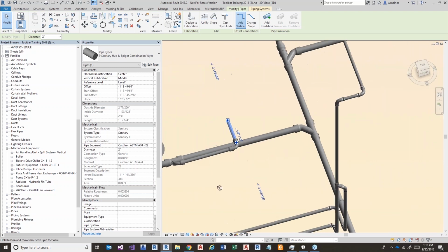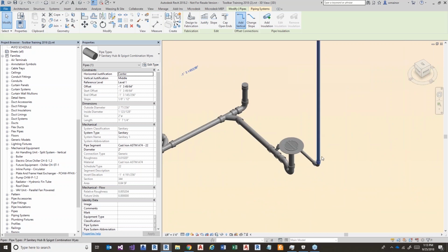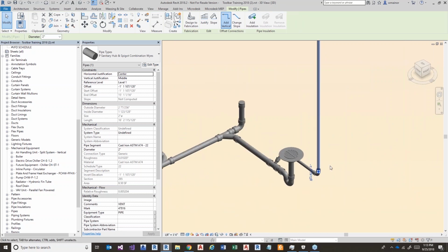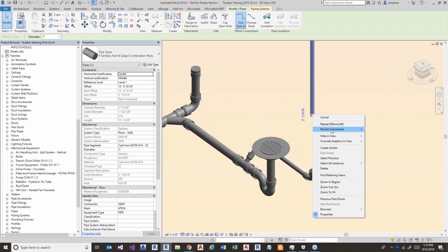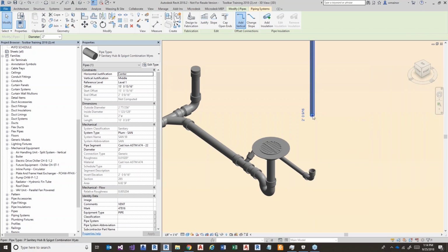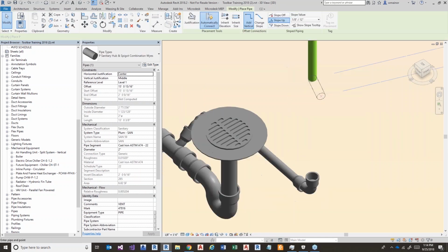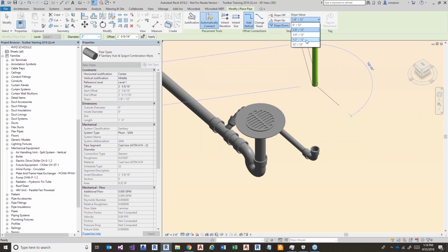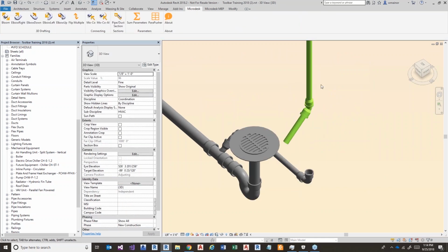So eventually what I'm thinking is I probably have another vent line which I need to come off at a 45-degree angle. So let me just come up here. I'm going to pull this guy up, right-click on the connector and draw. Whoops. Make sure I get the connector. Draw a pipe. And now what I'm going to do is slope down, and I'm thinking I'm going to come down at a 45-degree angle. I'll get a fitting something like that.